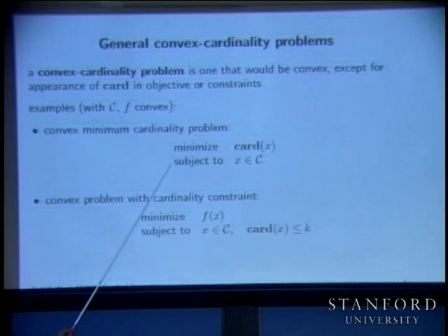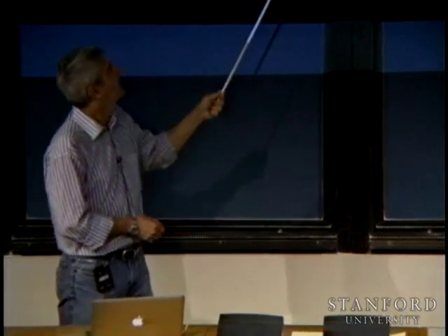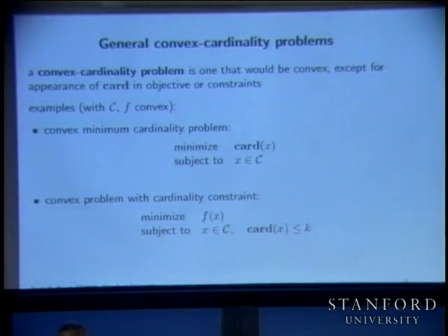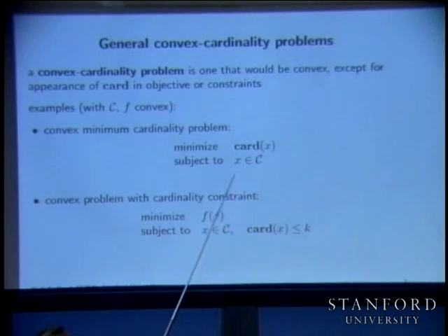It comes up in engineering design as well. So here, for example, the x's are often things like widths of wires, let's say in a circuit. And if a wire has 0 width, it means the wire isn't there. So it's basically saying, make me a power supply distribution network or a clock distribution network. Obviously, you can't give a tree, because if you give a tree, you can't remove any wire segment. So you give a mesh. And then you're basically saying, find me the sparsest thing that will actually satisfy all the specifications. Okay? So this comes up lots of places.